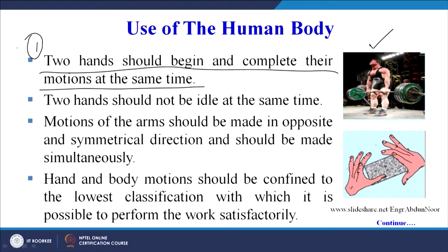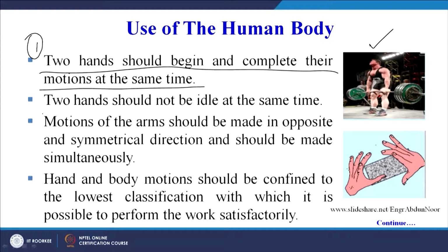If two hands are being used for conducting a work, they must start and finish their motions at the same time. Two hands should not be idle at the same time. So if you see, I am recording this lecture, if one hand is at rest, the second one I am using to highlight what we are discussing. So the two hands must not be idle at the same time when the worker is on the shop floor.